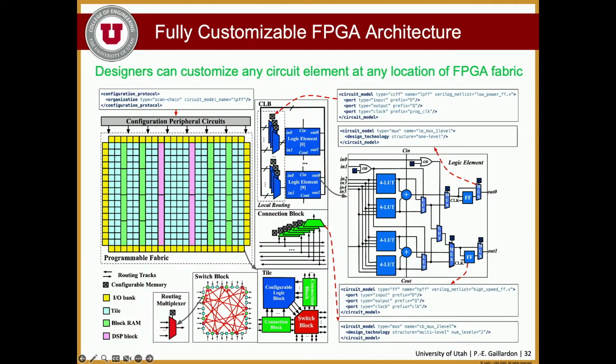Now, all these memories, I want them to be programmed using this brick, and I want them to be structured in a scan chain, whatever. I pass on the hardware details, but the idea is that you can describe whatever you have in your topology, in your architecture. Now from there, the tool can go on its own and generate the actual internal representation. It can generate bit streams.